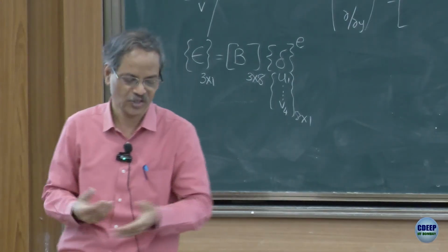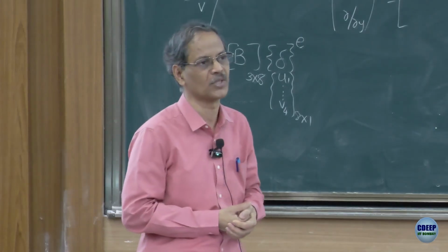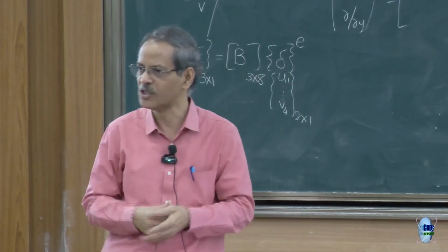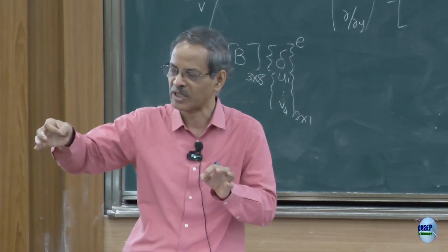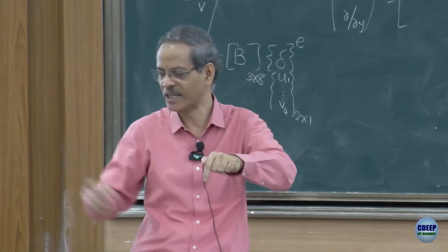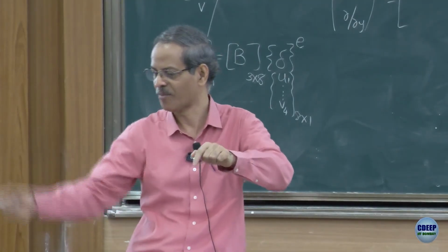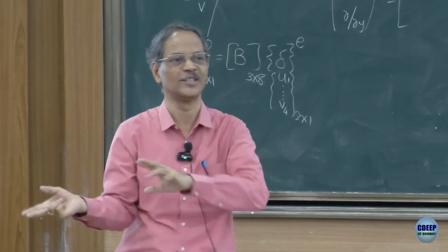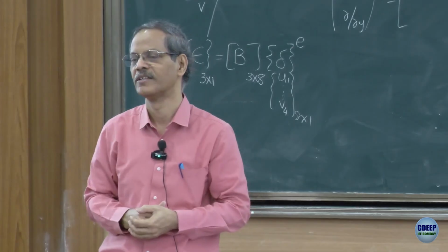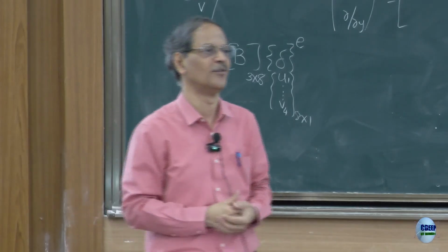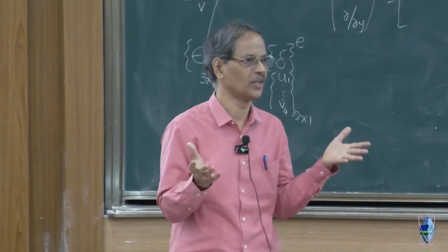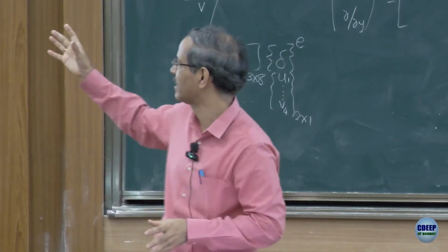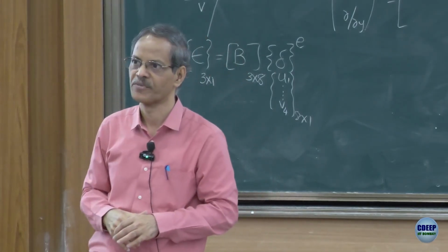In structural mechanics, this symmetry you may have come across in solid mechanics courses through some other principle like the reciprocity principle. That means, if I apply a load here and look at the deflection there, or apply a load there and look at the deflection here. This reciprocity relationship you must have either read about or heard about, the Maxwell-Betti reciprocal theorem and so on. So, that symmetry is what is reflected in these matrices again.